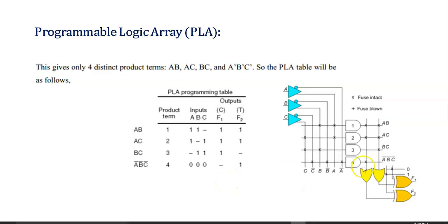So whatever function you want to complement, that way you need to program this XOR gate. So if you want to invert, then connect one of the terminals of the XOR gate with 1, and if you want to give it as it is, then connect it with the 0, and the rest of the input you need to connect to the output of this OR gate. So that way complement function is possible over here.